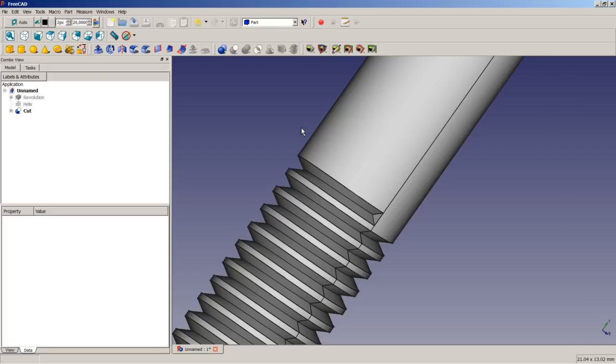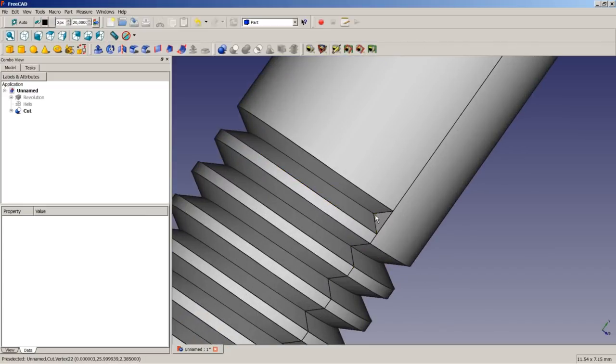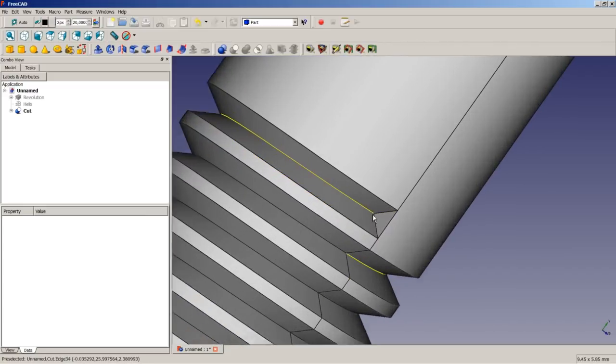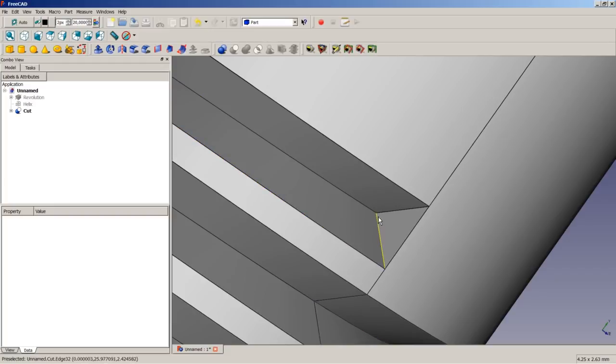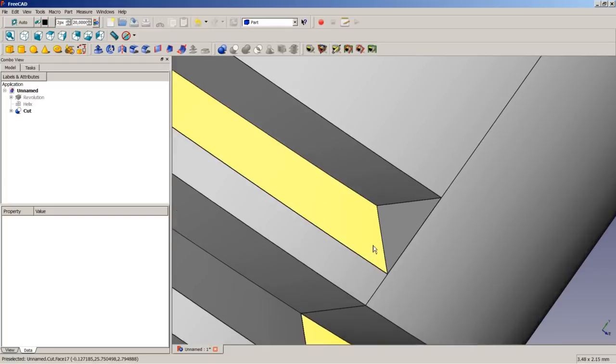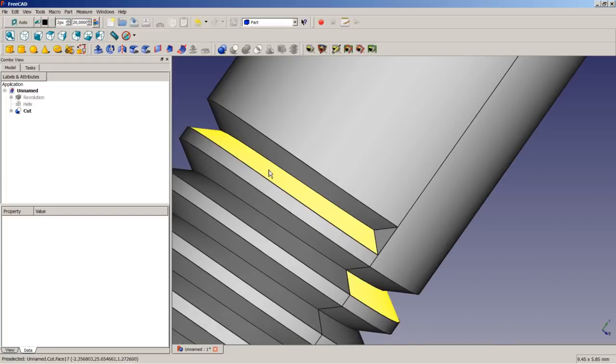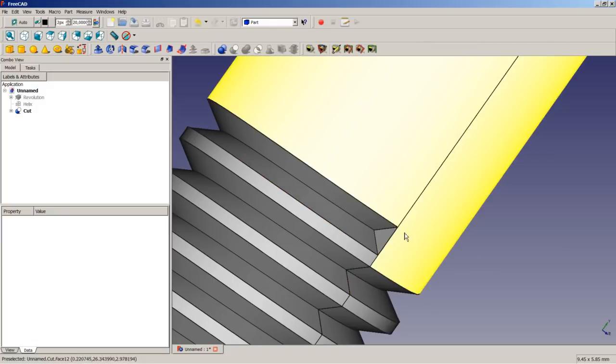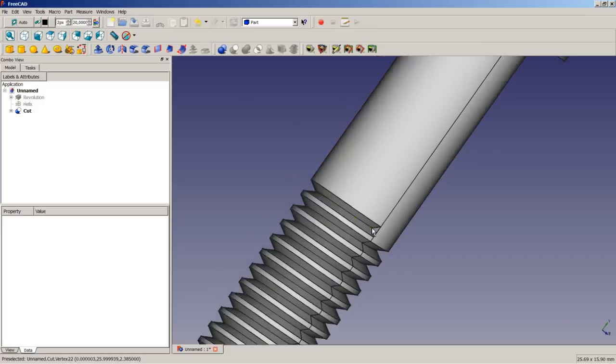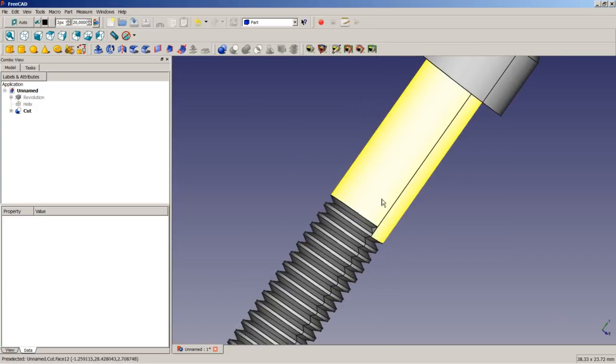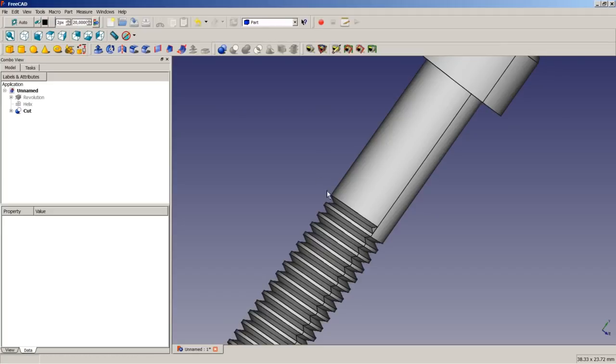And when inserting the second helix, if you will apply the correct dimension, in this case the correct dimension of this base point here in regard to the origin, which was, as you may remember, 2,385 millimeters, this helix operation, when applying the Boolean cut, will fail as well.